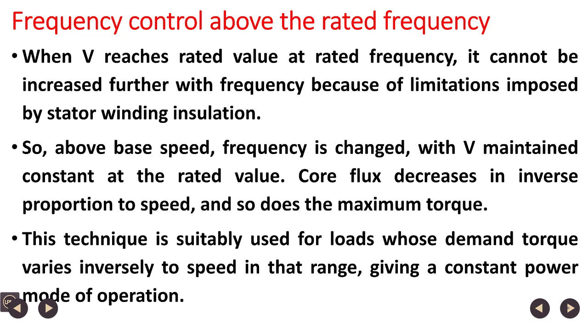Because the flux is inversely proportional to the speed or frequency, and maximum torque is inversely proportional to frequency, the load torque should be inversely proportional to frequency, so that power is constant. Speed is proportional to frequency, so motor torque should be inversely proportional to the speed. So, it is suitable for a constant power load. So, this range of operation gives constant power mode of operation.